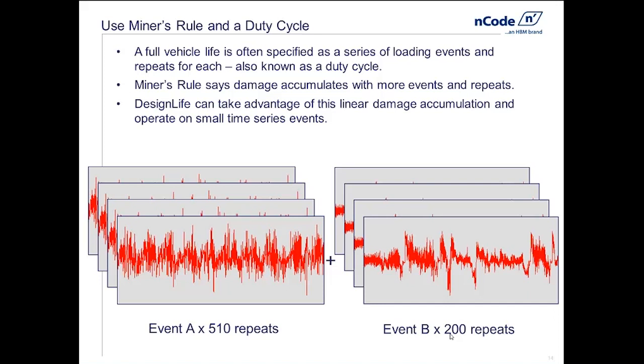Likewise, Miner's rule says fatigue damage adds up. So we're going to use that to our advantage. DesignLife has Miner's rule built into it, and it has what we call a duty cycle mode that I'll show you in just a minute that will allow us to calculate damage for event A and then scale it up by a factor of 510.